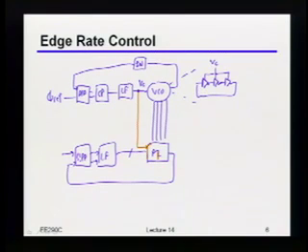Okay? Now, by the way, what does that imply about how I should be building the phase interpolator? If I'm relying on this VC right here to set an edge rate inside of the phase interpolator, how should I build that phase interpolator? What sort of circuits should I be using? Ring oscillator. Okay, basically I should be using whatever's inside of the ring oscillator.